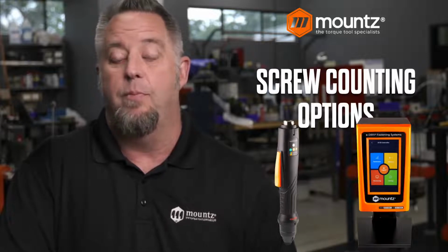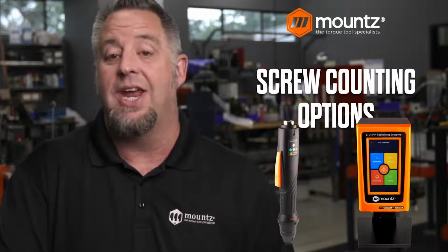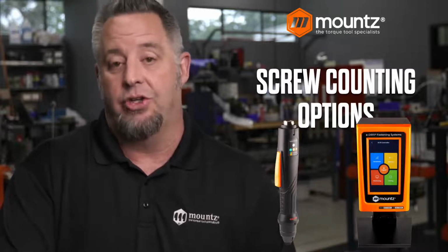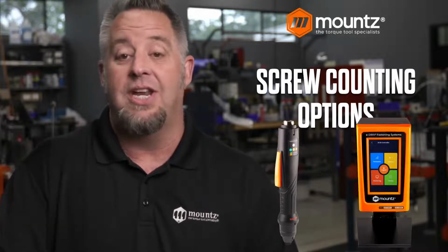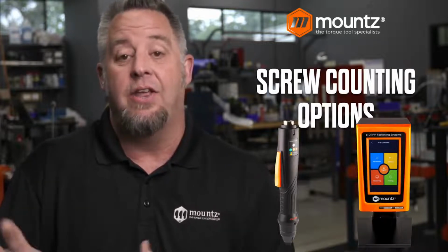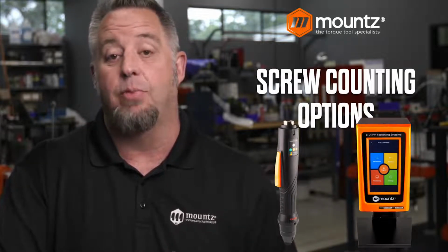So if you have multiple presets that you might be dealing with and multiple fasteners, we can build presets around those particular fastening items. So we have our torque, you have the screw profile. All of that can be encompassed in an assembly program that will allow you to do that in a certain order, and then the controller will automatically change the preset based off of the assembly process.